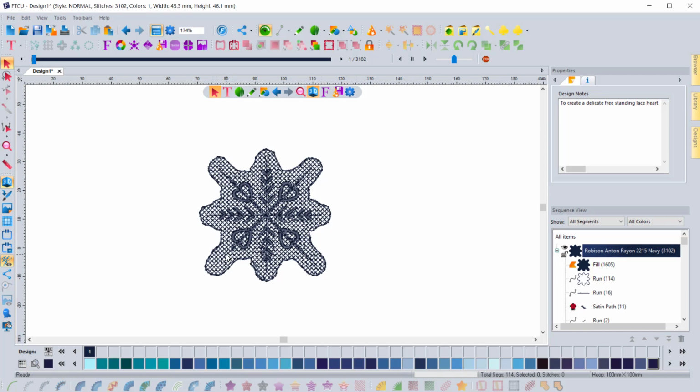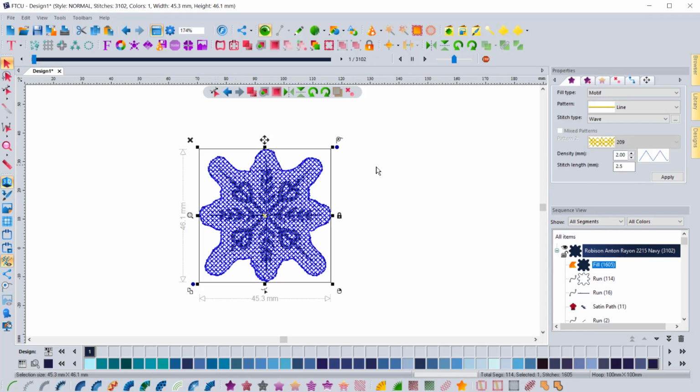Before it kind of just did a default amount, so that's kind of a nice little feature that you can choose how much of a distance you want, and you definitely want to have a little bit of distance because you want to make sure the stitches don't fall into the nap of any of the fabrics, and you don't want the nap of the fabric to come over the top and hide the stitches. So that's the point of having it kind of offset. And 2.5 is the default amount.